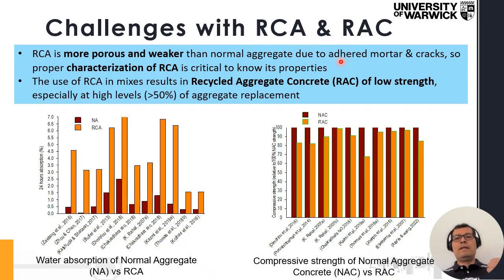One of them is the adhered mortar, because this is basically recycled material from an old concrete. So there is always some mortar attached to the little bits of aggregate we get. And that increases the porosity. And therefore that absorbs more water when it comes to the mix and the mix design.